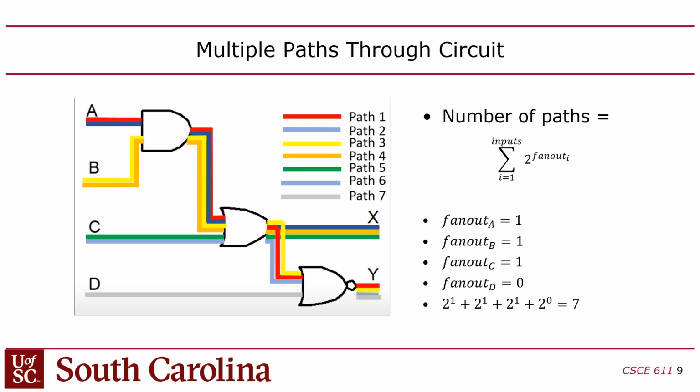Is there a maximum fan-out? I don't think so. It's a good question. It lists the fan-outs, though. If you look at the reports when you synthesize your design, you can find all the fan-outs. You can find the highest fan-out nets. Obviously, clock is the one that fans out the most because it connects to all the registers. But that clock is usually routed on special wires that are designed for high fan-out. For regular nets like this, regular signals, you can get a listing of the fan-outs.